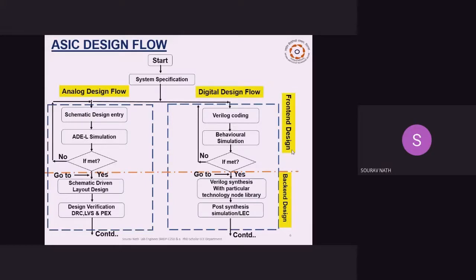After that, post synthesis simulation is done, or LEC. After synthesis, logical equivalence check is done, to get confirmation of the Verilog coding along with the synthesis netlist, whether it is one-to-one mapping or not.